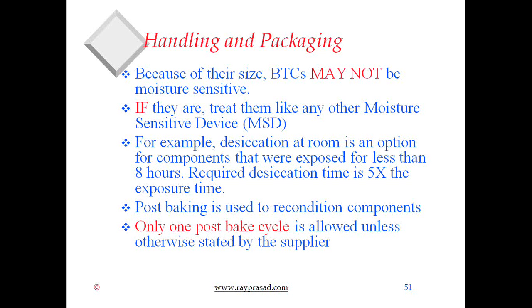And there are times that you can do the desiccation, meaning if it's been exposed for 8 hours, you can have it in a desiccant for 40 hours and it will take the moisture back. But that's about it. And a lot of the time people think, well, we can bake it to recondition the package. That's really a bad idea, because every time you bake the package to take the moisture out, you are going to reduce the solderability, and it's bad enough already. Remember, it was already baked by the component supplier one time.